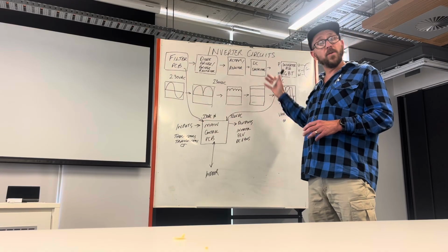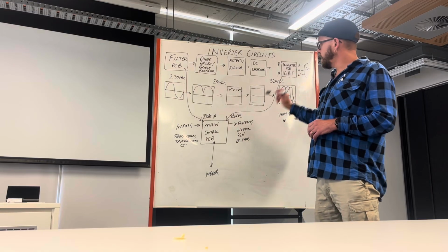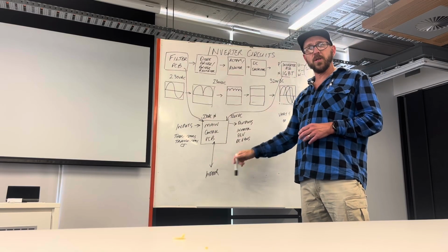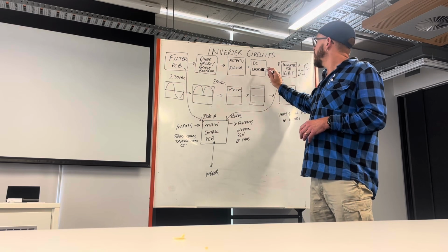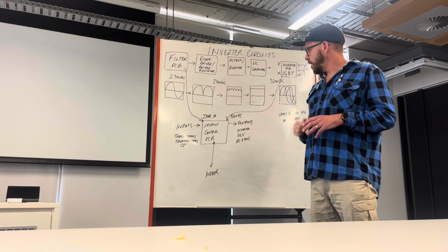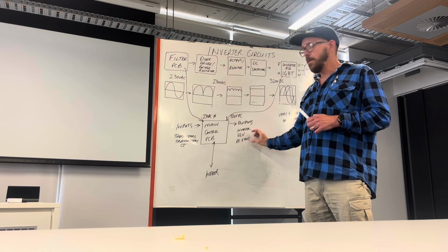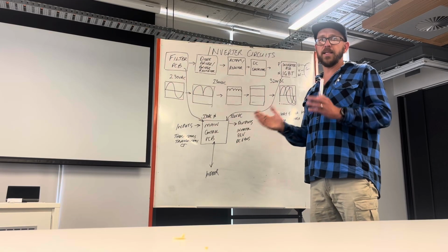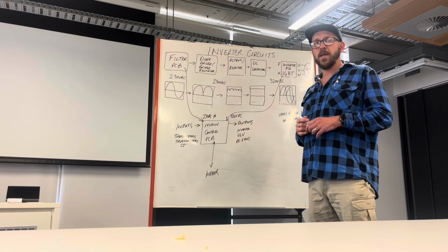So that's just the outdoor, but you'll find a lot of the indoor units, especially on the big ducted, where they're running DC fans, they're going to have a lot of this componentry as well. So you've got the AC going in the indoor unit. Again, there's going to be a diode bridge in there, changing the AC to DC. There's going to be capacitors. There's going to be some form of inverter, or like the DC fans here, they've got their own inverter board built into the back of the fan motor. So they're getting a signal from the control board to run, telling it how fast and giving a signal back that it is running, but it's got its own board in those fan motors speeding it up and down.